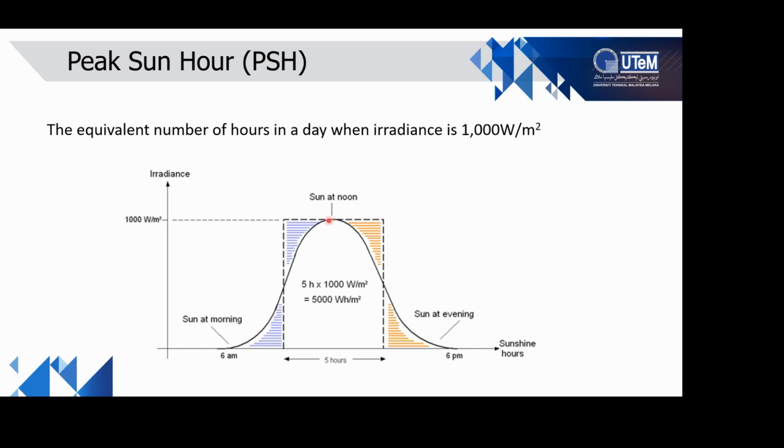Okay, if we increase our PV capacity and we keep our inverter at a smaller rating, for example, if we want to generate 1 megawatt, we use a 1 megawatt inverter, but our PV capacity is 1.5 megawatt. What happens, especially during noon, at the top part here, some of the amount of energy will be clipped. Clip meaning it will not generate power.